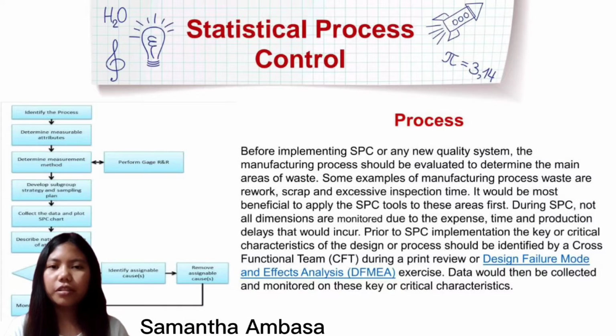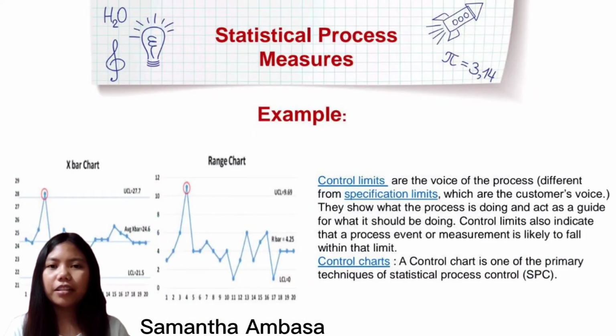3. Determine the measurement method and also perform gauge R&R. Create a measurement method, work instructions, or procedure including the measuring instrument. For example, consider a thickness gauge to measure the thickness and create an appropriate measuring procedure. Perform gauge repeatability and reproducibility (gauge R&R) to define the amount of variation in the measurement data due to the measurement system.